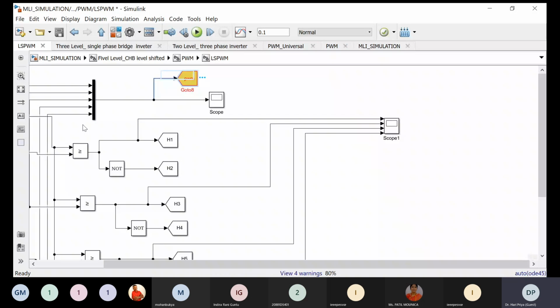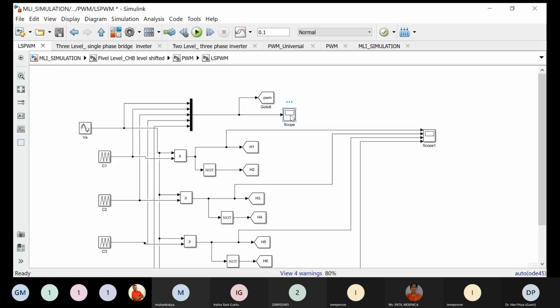One of the popular methods for doing it is the level shifted PWM technique, where we use multiple carrier waves. Now in this case, I want to generate 5 levels, so I will use 4 carrier waveforms and distribute them evenly with respect to the overall modulating signal.